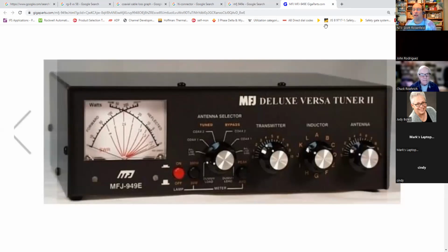So we could actually calculate this mathematically, or we could get an antenna tuner that has a dual needle watt meter that will tell us what it is. Some radios actually have an SWR calculator built into them. They will tell you on a graph what your standing wave ratio is.